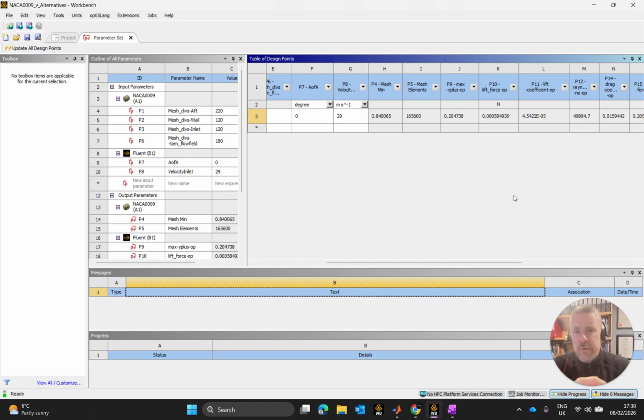And same thing with pressure coefficient. The thing there that I am really concerned with, that I'm really interested in, is the drag coefficient and the drag force, because when I pull the trigger and I shoot the car down the 20-meter track, after about 0.4 of a second, I'm out of gas. Right? The 8 grams of CO2 is now exhausted, and I've lost thrust.